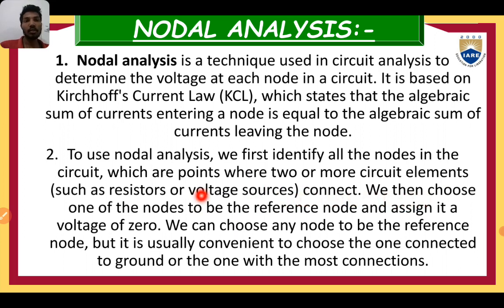We then choose one of the nodes to be the reference node and assign it a voltage of 0. We can choose any node to be the reference node, but it is usually convenient to choose the one connected to the ground or the one with the most connections.